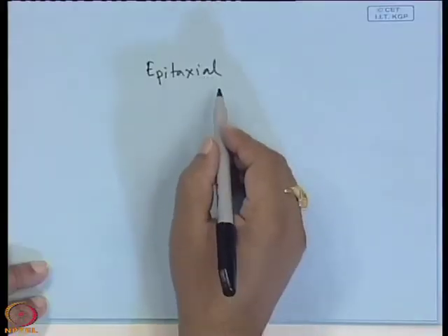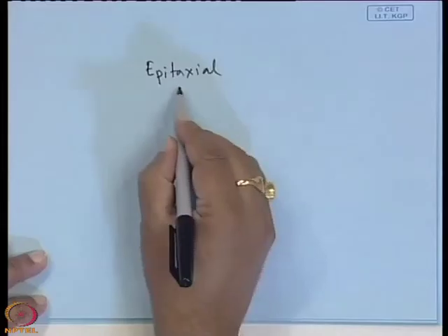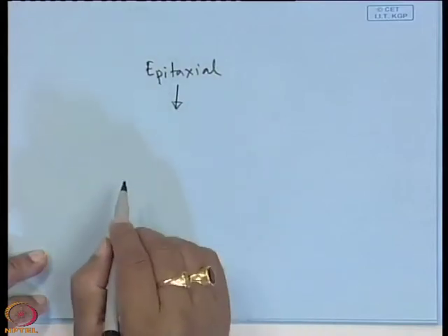That kind of precise doping concentration and precise thickness is not possible in case of bulk crystal. Epitaxy means a single crystal layer, very thin layer of some nanometers, some angstroms, 100 angstrom, 200 angstrom, 400 angstroms, right. So, how are the epitaxial layers grown?